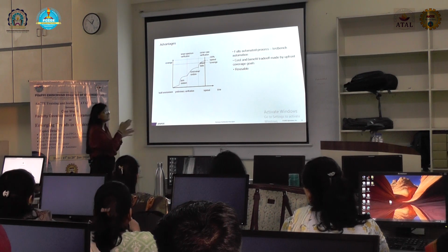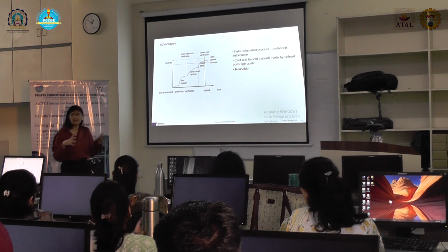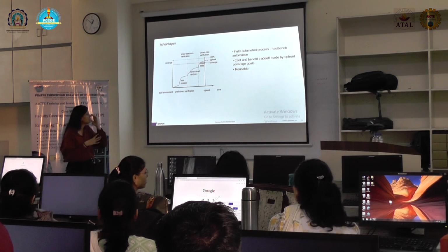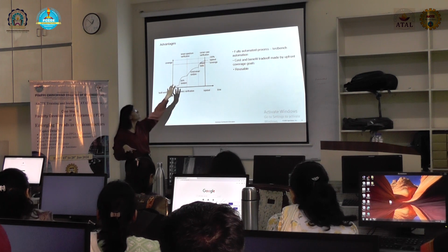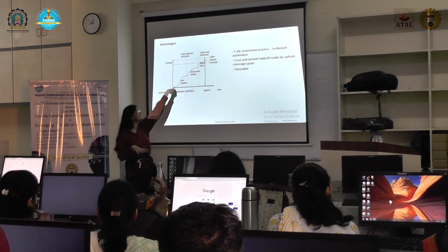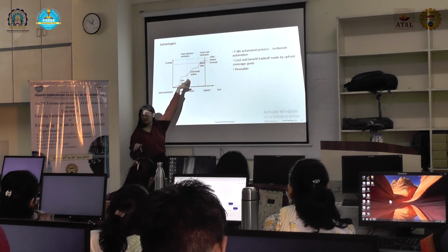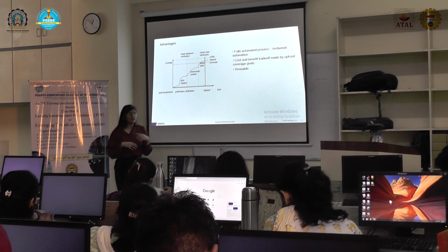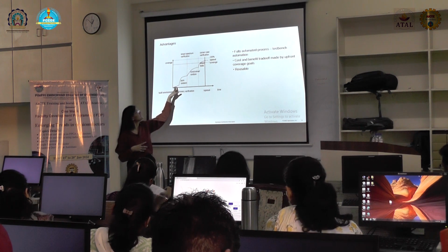So what is the actual verification cycle when we are involving coverage and verifying the full tape-out cycle from the perspective of verification planning? Initially we run regression test cases on pure random scenarios. Pure random scenarios will increase the verification goals or coverage data significantly, because multiple things are randomized and multiple coverage bins will be hit for particular scenarios. So we start with pure random scenarios.